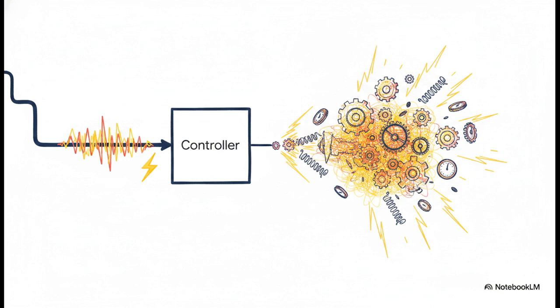It watches how fast the process variable is rushing toward the target. If the temperature is suddenly dropping really rapidly, the derivative term sees that steep slope and actually subtracts from the total output, beautifully slowing down the approach to prevent you from blowing right past the target.